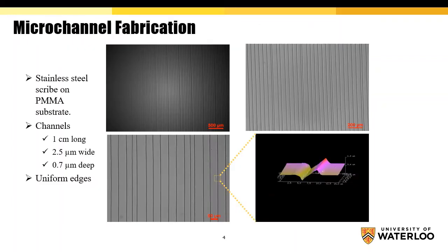We are also using our dynamic scanning probe lithography method for fabrication of microchannels and nanochannels. You can see in this slide the microchannels fabricated on the PMMA substrate. Those channels are 1 cm long, 2.5 micrometers wide, and 700 nanometers deep.